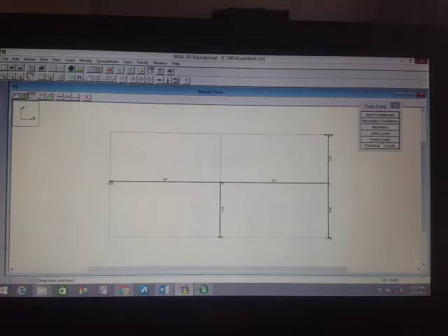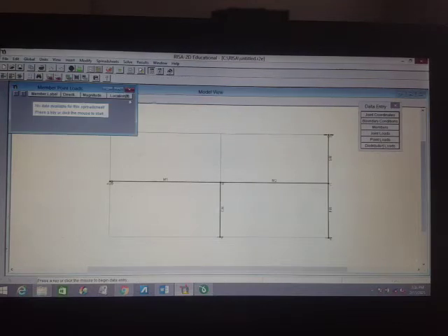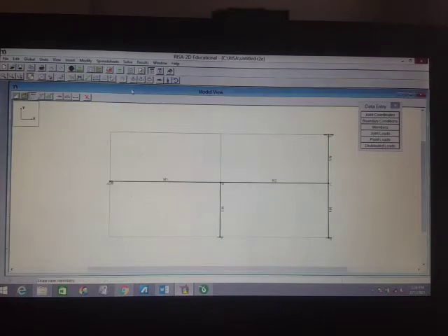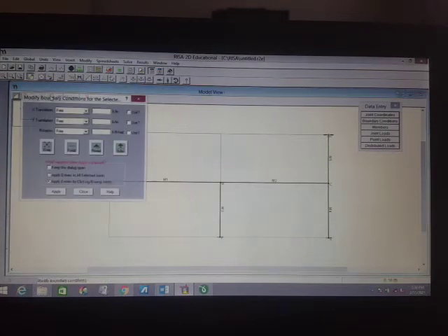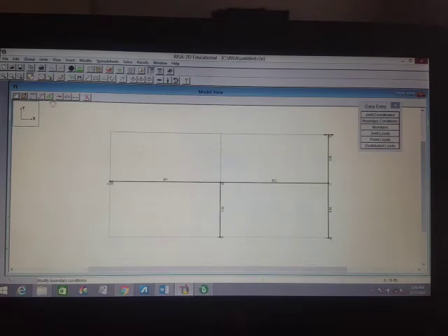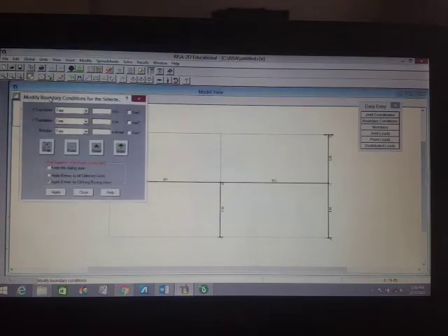Okay, so point loads. So we have a point load of 32 kips. Okay, so we'll click this, or we can also, by the way, you can also construct the boundary conditions in terms of this. You can just select free, fixed, pin, or roller.